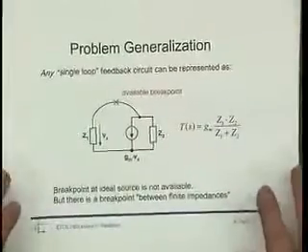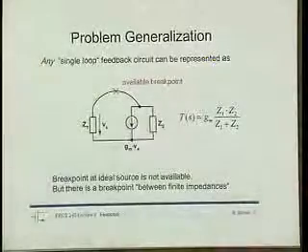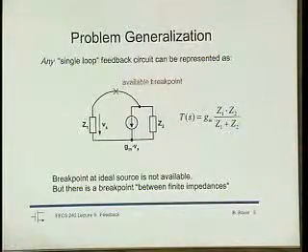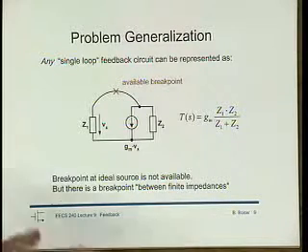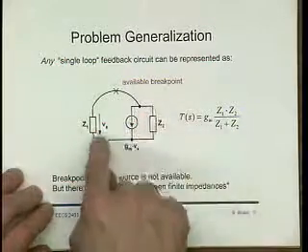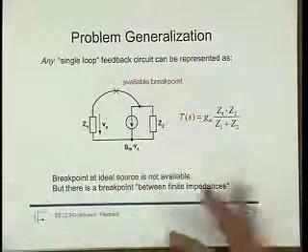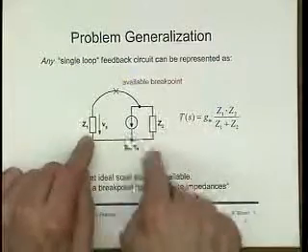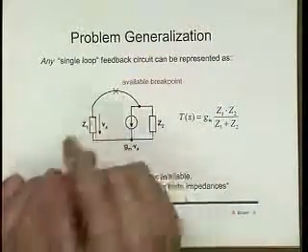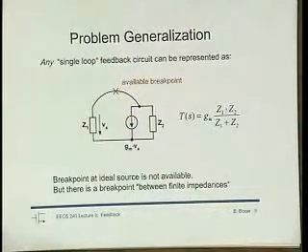So now it becomes a little bit more schematic, but in reality it's really the same thing. Here we are breaking up the circuit also into two ports, but not into the amplifier and the feedback network, but the amplifier and the feedback port. Anyways, we are separating the circuit into two ports, and there is a connection between them that, when we break it, opens the feedback loop.